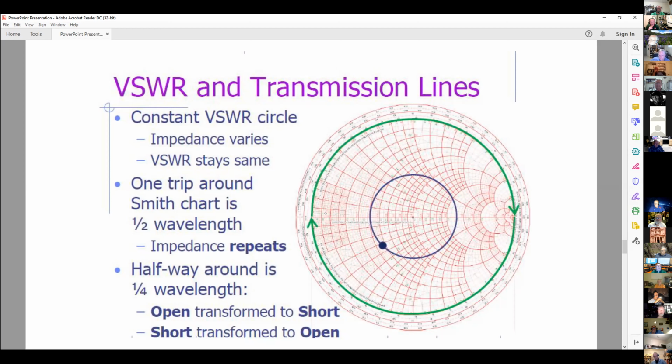So if your load is not perfectly matched and you have a quarter of a wavelength, or an odd multiple of a quarter wavelength line, you can get this impedance transformation, which can make it difficult for your rig to accept power. And again, the visualization here is you're traveling down this transmission line, seeing the impedance change as you go. That is correct.